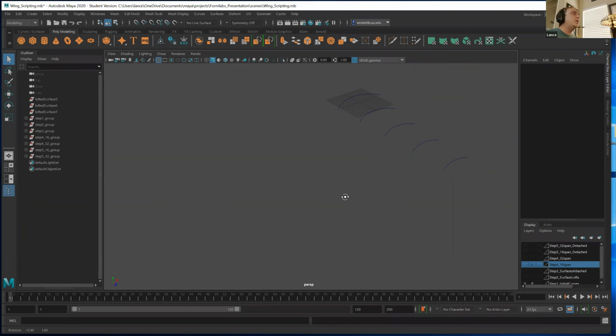So there's a couple of different curves here. And I am an advocate, and I use constantly a modeling tool set that a lot of people laugh at and think is dead. It is called NURBS, stands for non-uniform rational B-splines. We're not going to go into an entire lesson on why NURBS is really cool, but let me just use a couple of key points here. One of the reasons why NURBS is powerful is that it's a curve-based modeling tool set, which means anything that you might use from Illustrator or an SVG file, logos, those curves can be brought into Maya as NURBS curves.